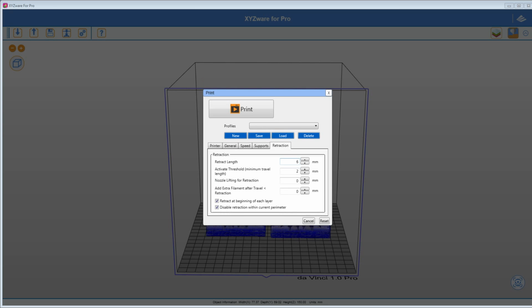And the last button is your retraction. And with retraction, this is a Bowden style setup extruder. It is not as long as the Ultimaker for the tube size, but it is probably a 100 millimeter long tube. So you're able to adjust some of your retraction settings. Again, if you guys are just starting printing, you don't really need to modify this.